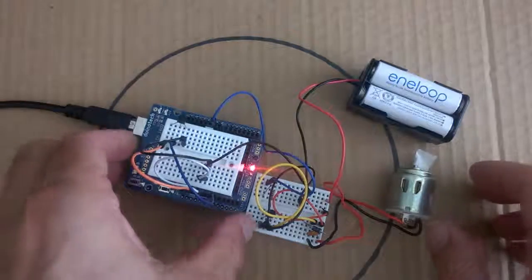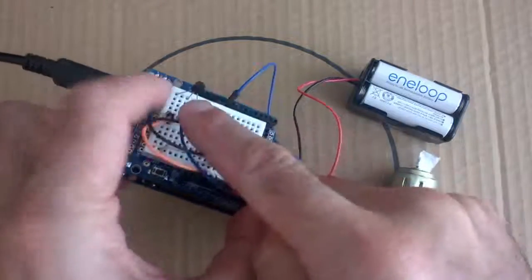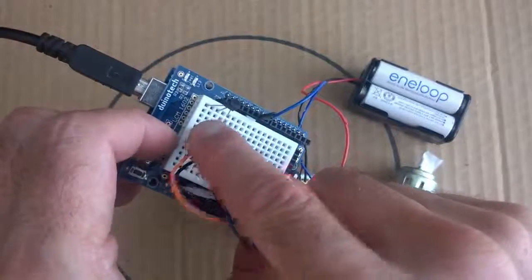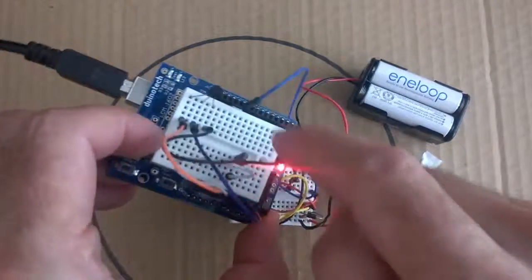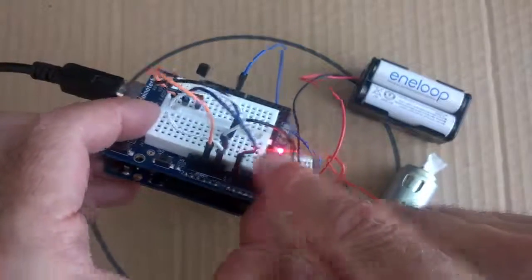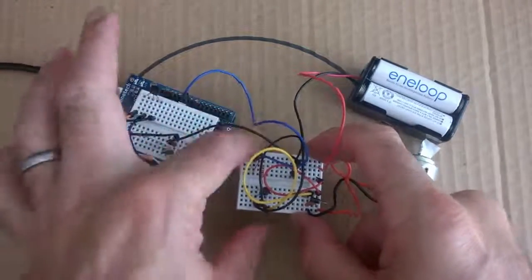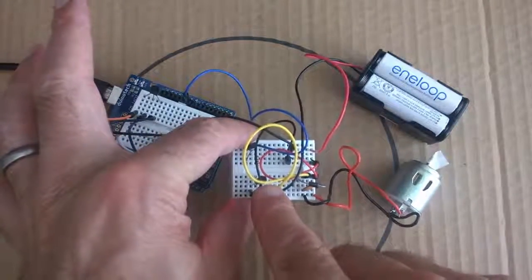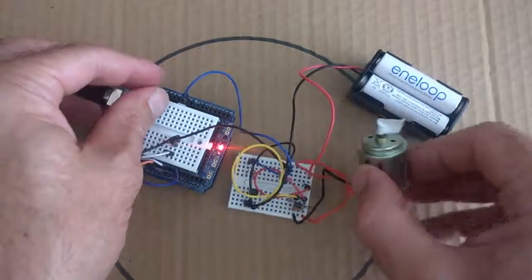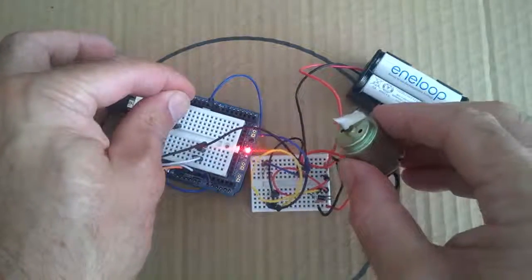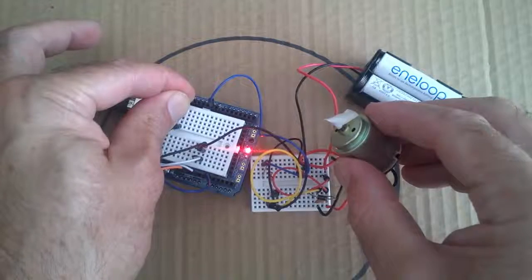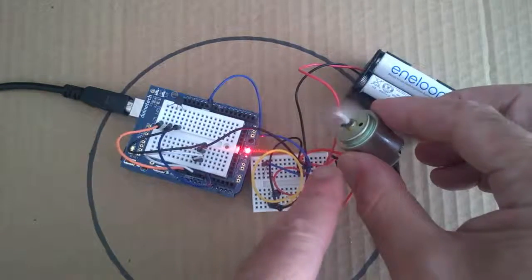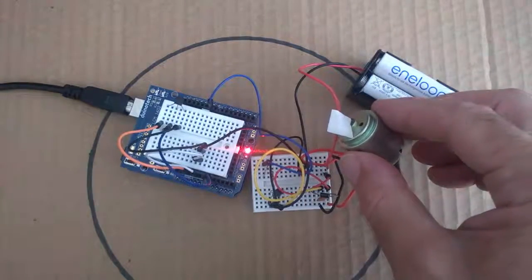In this circuit here, I'm using a TMP36 temperature sensor, which is connected to the 5 volts on one side, ground on the other, and the middle pin to the analog 0 port. This is connected up to one of our previous circuits with our DC motor and our NPN transistor as a switch, so that when the temperature sensor reaches a certain point, the DC motor goes on, and when the temperature drops back down again, it switches off.